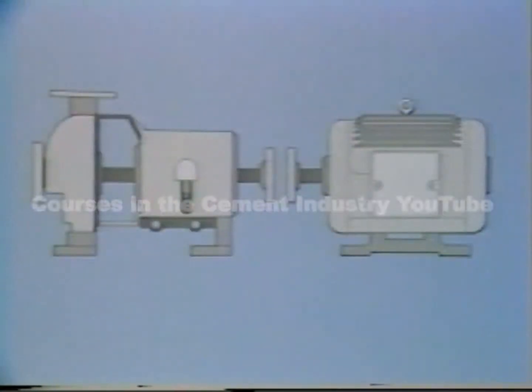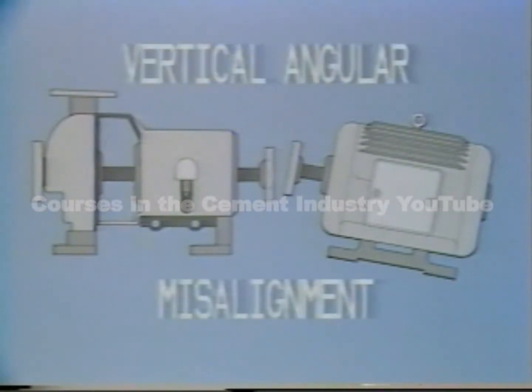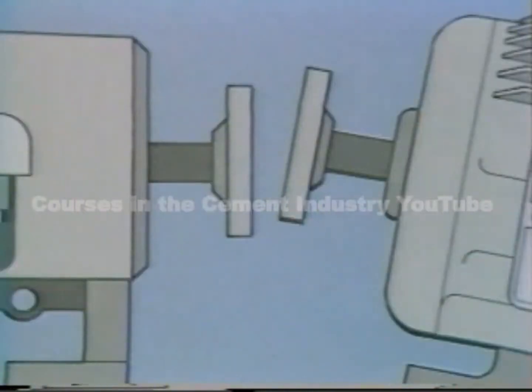Here's the pump and motor combination, and we're looking at them from a side view. Now, suppose we assume they're in perfect alignment right now. If the motor tilted like this, what type of misalignment would we have? If you're thinking vertical angular, you're right. Notice the angle that has formed between the two shafts when looking at them from a side view.